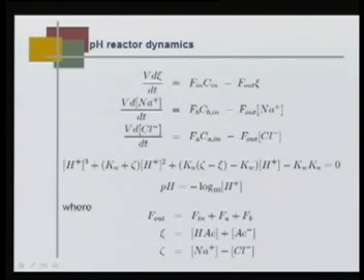So, this equation is a function of zeta and xi, the states of this equation. I solve this equation, and then I put this zeta and xi in this equation, and Ka is an external coefficient, Kw is another external coefficient. By putting this, I solve for H, which is a nonlinear equation, and then pH is minus logarithmic of H plus to the base 10.